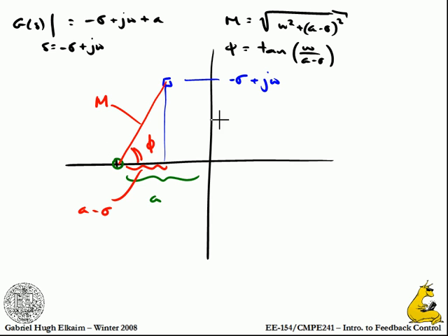And I can now start looking around, and I can say, hey, if I need phi to be 180 degrees, that's pretty easy to identify. To get phi 180 degrees, I know I have to be here. How do I know? Well, because that's the only thing that gets me to 180 degrees. I can see here that as I bring this point down, phi goes to 0. As I bring it around to this side, phi goes to 180. If I needed phi 90, I'm right above this. I can look at this angle and immediately figure out where I want to be. Hey, this is getting better.